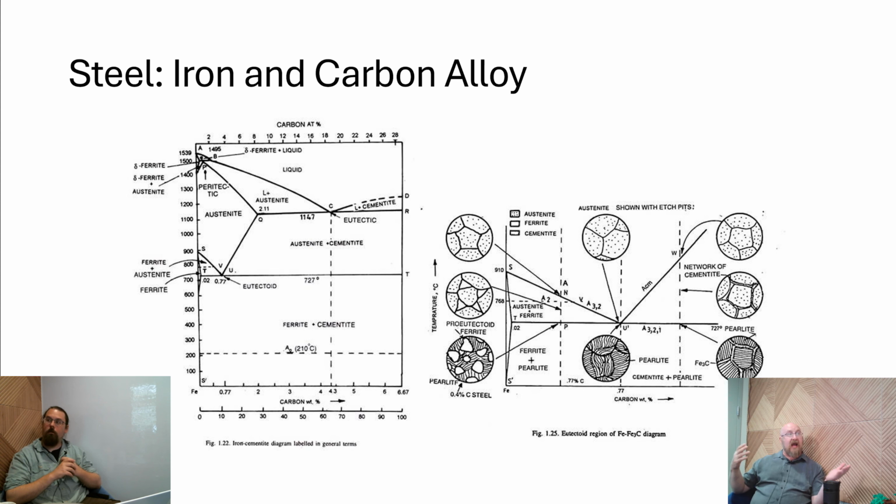Because what would happen if we allowed that carbon to come in physical contact with this steel alloy that is above 1147 C? I think we were doing it at about 1600 C. And the thing here is, as long as you're above this critical temperature, this reaction is nearly instantaneous.